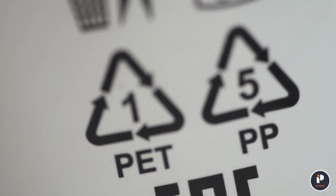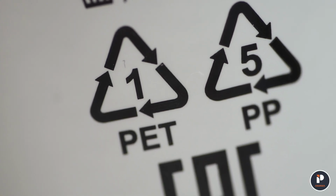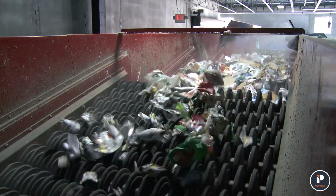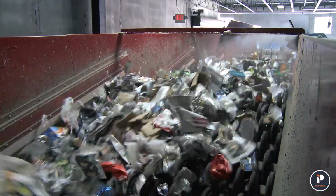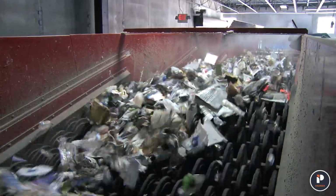For example, when designing for recyclability, it is important to choose a base resin that is desirable for recycling, such as PET, HDPE, or polypropylene. The size and dimensions of a package are important due to the size limits of recycling machinery, particularly automatic sorting equipment within a material recovery facility. For example, if a plastic part is more two-dimensional than three-dimensional, it may have the likelihood of being sorted into a paper stream instead of plastic.